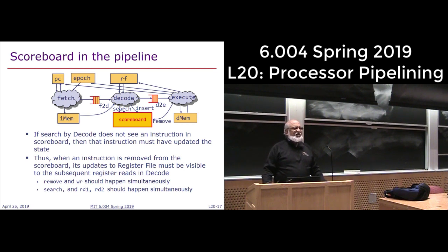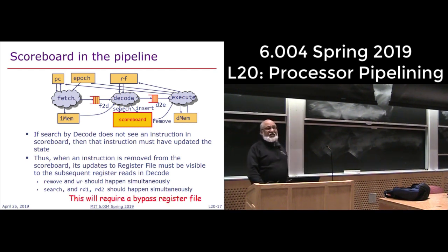All right? What is subtle here is, if in this cycle I'm writing into the register file, and in the same cycle I'm reading the register file, what am I going to see from the register file? Does anybody remember, in the same cycle, if I do an update to the register file and I read the register file? Yep. The read happens before the write. The read happens before the write, right? So read happens before the write. That's the basic register file we have designed.